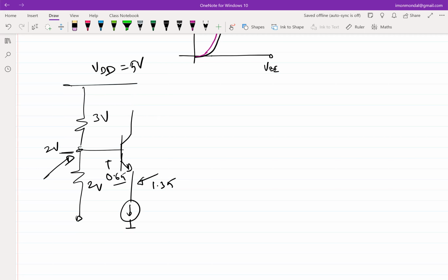So then if you want to connect a load here, you put some RC, right? So the value of the RC will depend on what? While you want to keep this device in proper working condition, the active region in this case, it will depend on how much current source you have here and what is the drop across RC. And how much can VC drop before the device goes out of your region of operation? We are trying to keep it in active region.